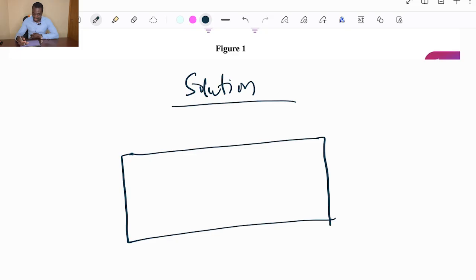Before the PN junction is formed, you have to take a semiconductor and dope one part of it. For example, you have a semiconductor here. One part of it, you dope with P-type impurities. So here you have P-type impurities.